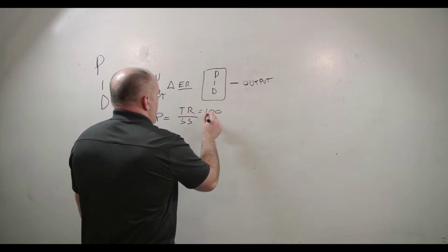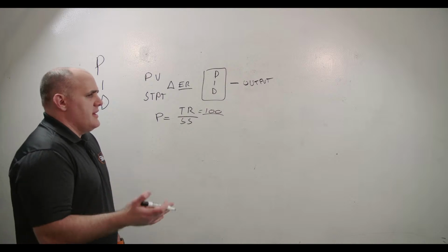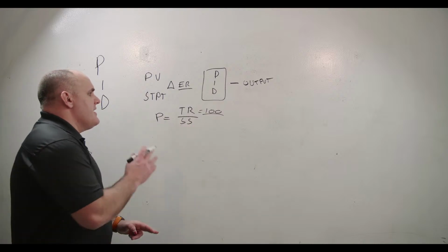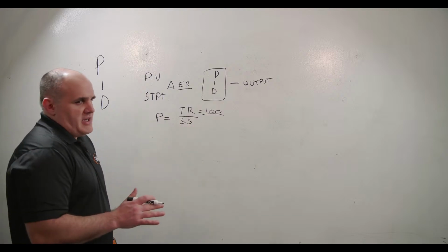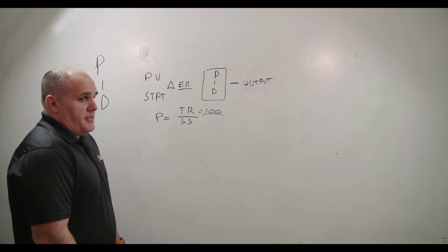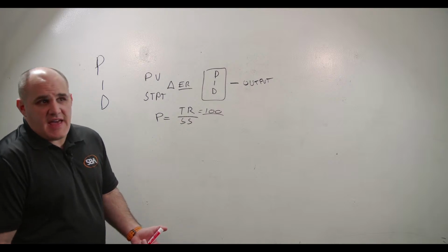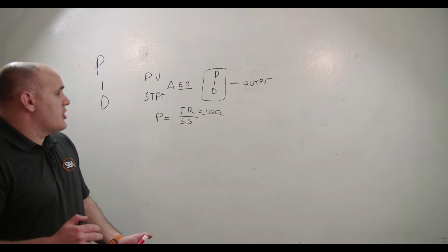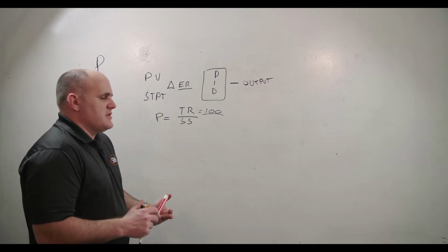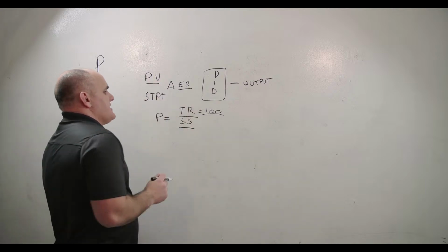And most of the time, our throttle range is 100%. Like when we're using 1/3, 2/3 valves in steam control, we may have different throttle ranges, but most of the time it's 100%. Sensor span is where people get tripped up. If I tell you that you're controlling a pressure loop, like a 1.5 inch static, and you're creating that sensor span, you're like, okay, what is the sensor span? Because the sensor span is the controllable range of the process variable.